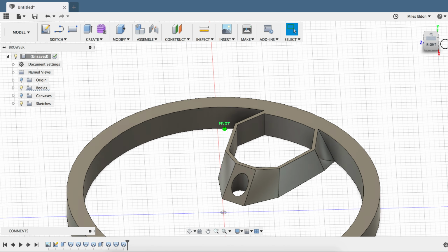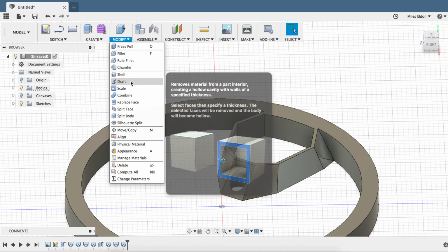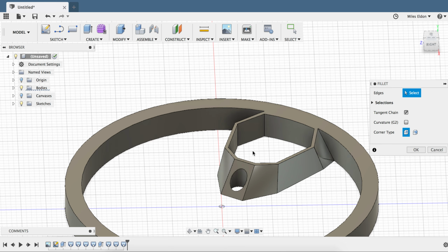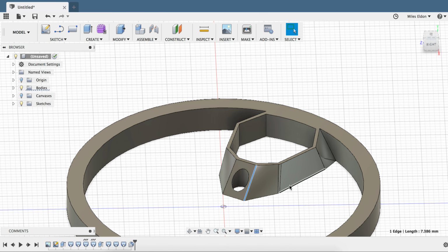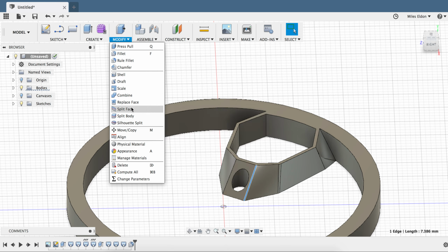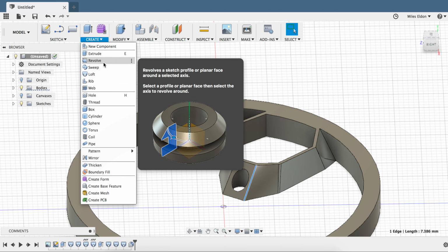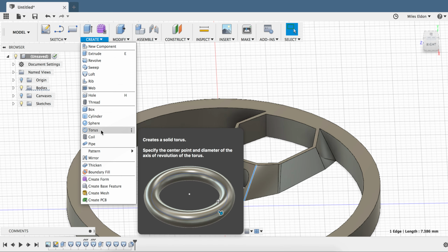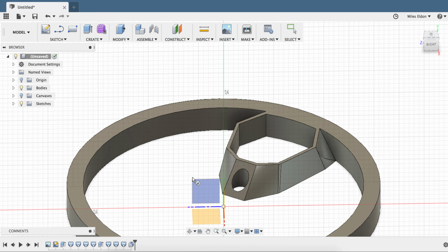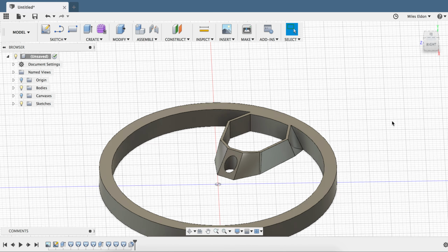Now, if we want to talk about finishing touches, like if you don't like all these right angles, we can smooth some of these over. We can, using the fillet command, and we could just say, hey, let's curve that edge. You can look at these other commands in here. If you want something that's a little more round of a tire, you can use a torus instead of drawing the 2 circles and extruding them. And that would look like, right here, boom. And then you draw the center, and you get kind of like a more tube-shaped thing.